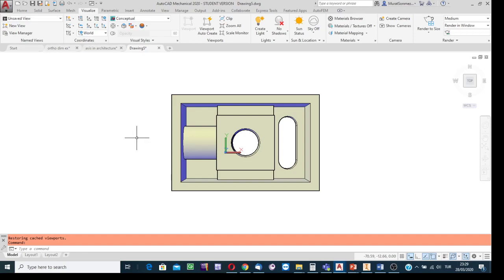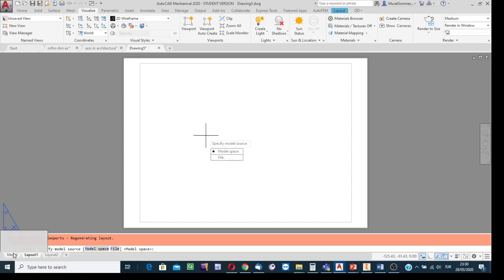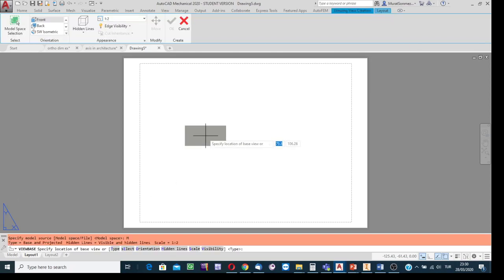See how the sectional view is created. Start the view creation process by writing this command, view base. Select this option, and AutoCAD asks whether we are going to use the existing model for creating its views. Yes, in the model environment the solid model is still active. I clicked on the model space button, and AutoCAD started to simulate one of the side views.